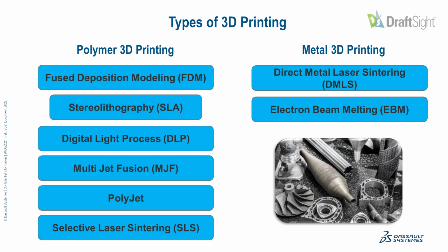Finally, we have electron beam melting, or EBM. This is an advanced process where, as the name says, an electron beam is used to fuse the metal powder together. The printing chamber is kept under vacuum, so a high-energy beam can melt the particles together, creating a homogeneous microstructure that results in high-strength parts.